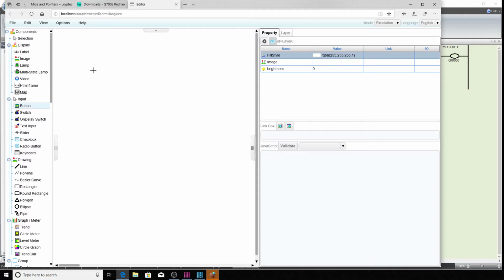First off, buttons are like buttons. They're momentary on, momentary off, whatever, depends on how you do it if you invert it. Switch is either an on or an off. You have to touch it to turn it on, touch it to turn it off. And I think that IDEC does it because of the latency between an Ethernet-based, internet-based program and a device like a PLC. It'd be hard to do a momentary for something that's got that much of a lag between it.